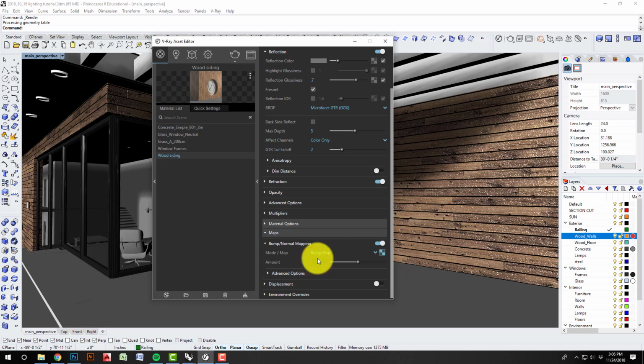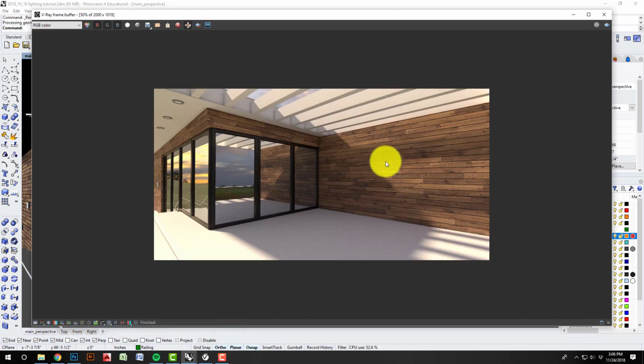You maybe go up to 1.2 or down to 0.8, and that usually sorts out it being too much. Sometimes I get textures that are feeling way too rough, I might jump into 0.5, but I usually don't have to do much more than that. This worked out great, that keeping at 1 was getting you this nice realistic wood texture that we want there.